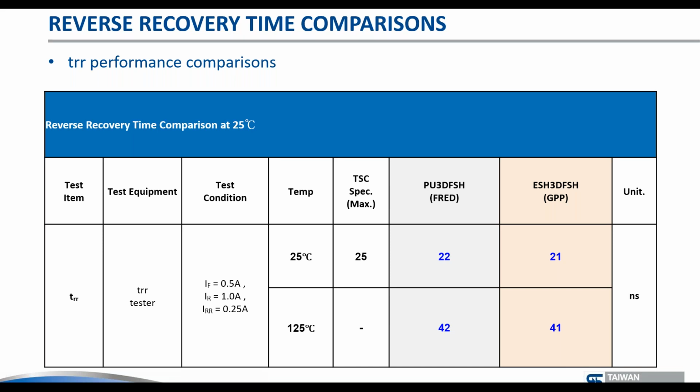And as a result, you can see that TRR, or I should better say the stored charge, has a positive temperature coefficient, and that is not known to everybody. So I'm diverting 1 minute just to bring this to everybody's attention.